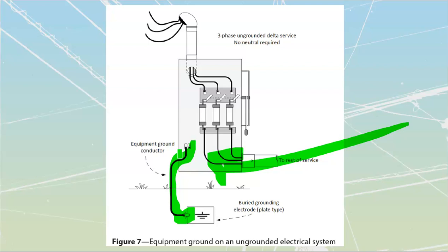We can use bus bars, we can use steel pipe, we can use rigid metal conduit, unless it's going to be made of stainless steel or subject to corrosion or damage, as well as we are allowed to use EMT. Once again, unless subject to corrosion or damage. So EMT in dry locations is going to be fine. EMT that is going to be in wet locations, used outside with weather-tight fittings, or EMT that is going to be placed into concrete slabs that are in contact with the earth or anything else like that.